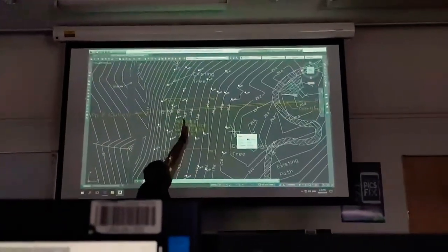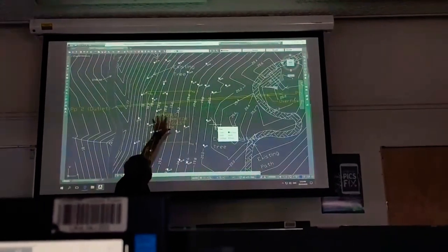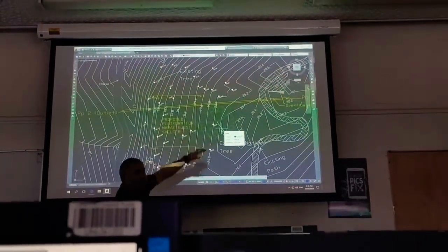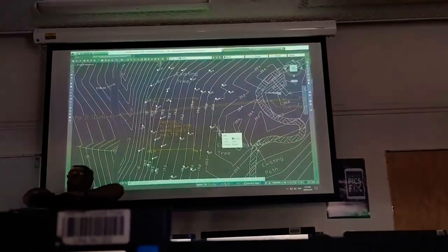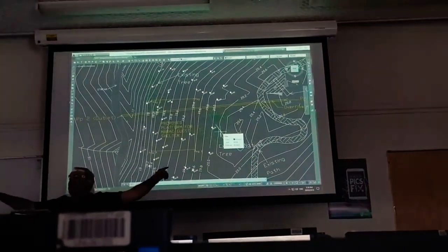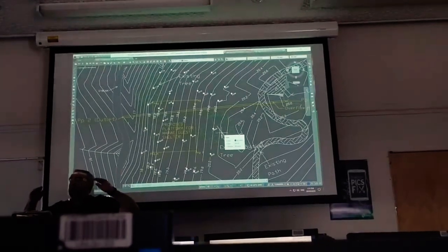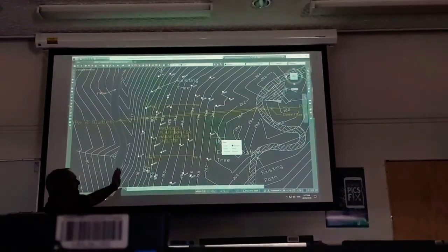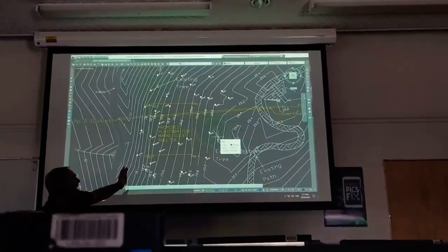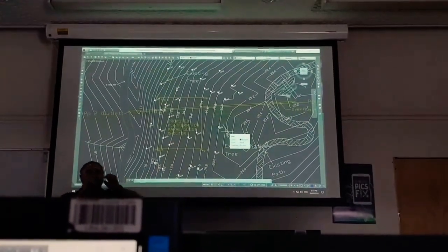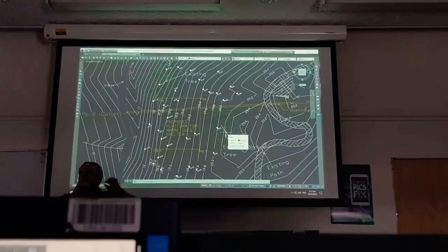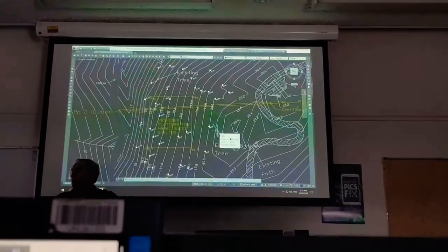If we do a section that way, it's pretty much going to follow 1 or 2 contours, which means the ground's going to be pretty much flat when you draw up the ground line. And it's in a fill situation from about 19 onwards, so there's not going to be a lot of platform shown. It's going to be a thin sliver of platform.